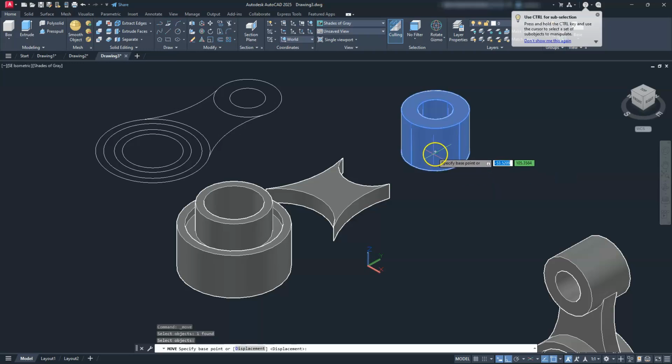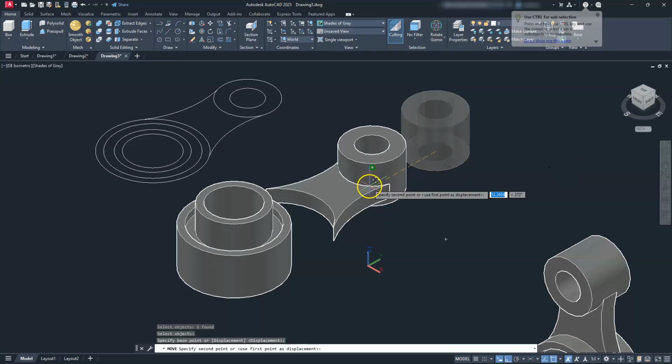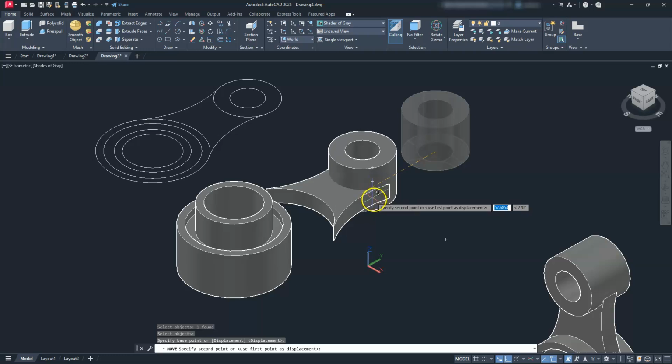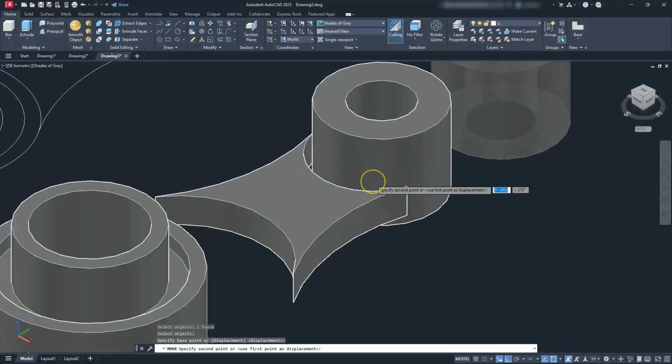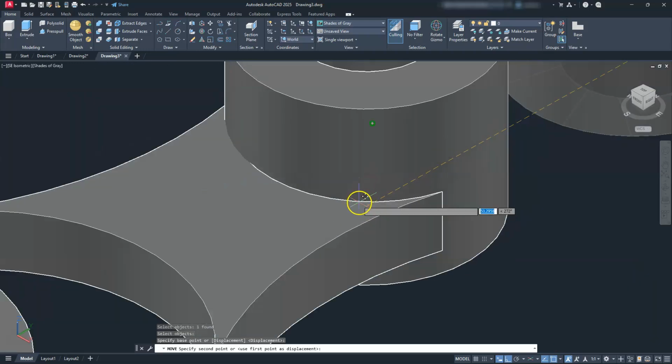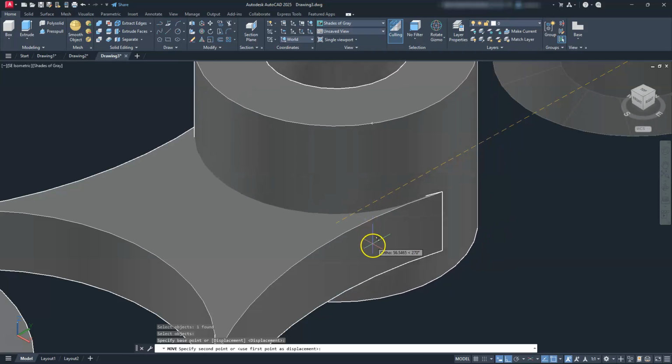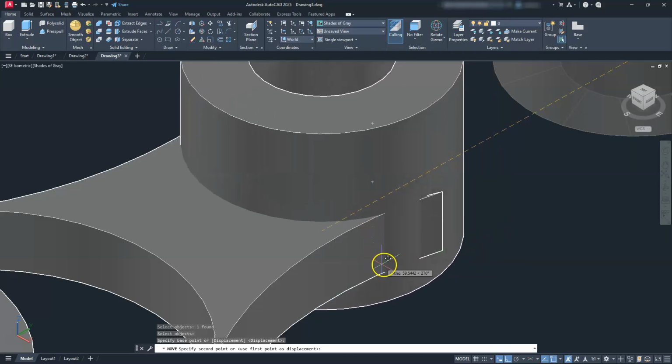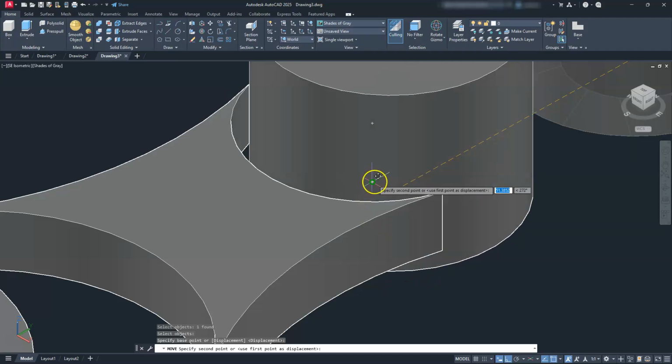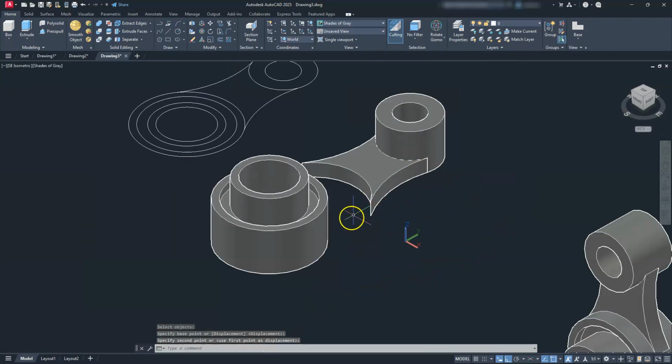Go find that bottom center, which is here. And remember that we're looking for two centers over here. Once I find that second center, and let me zoom in just so you can see them. There's the first one. If I move my cursor down here a little bit further, it should find that other center. Then I'm going to click on that center.